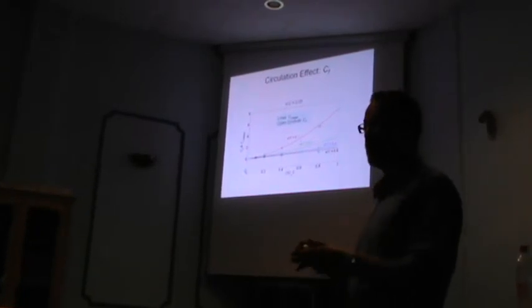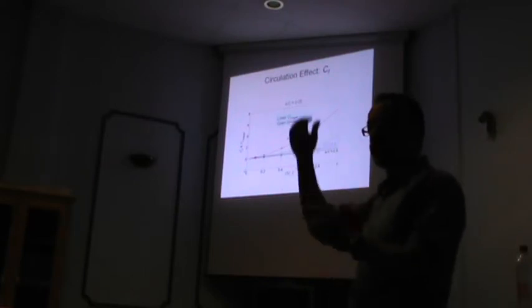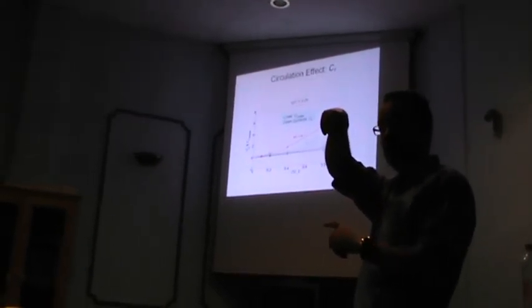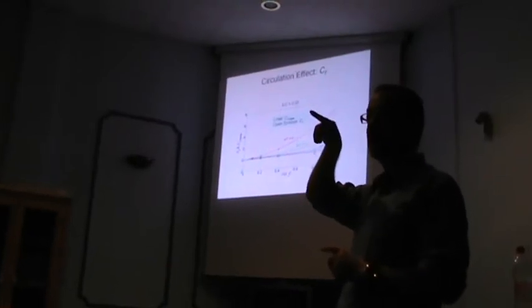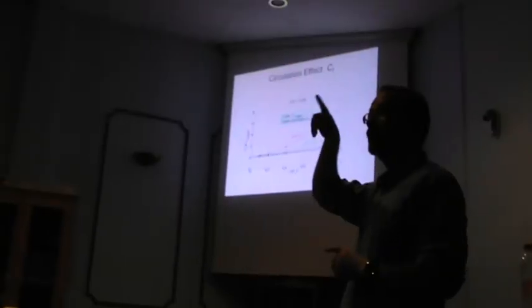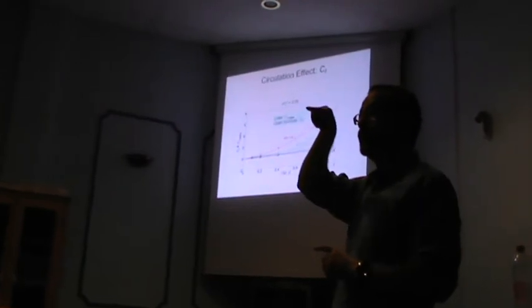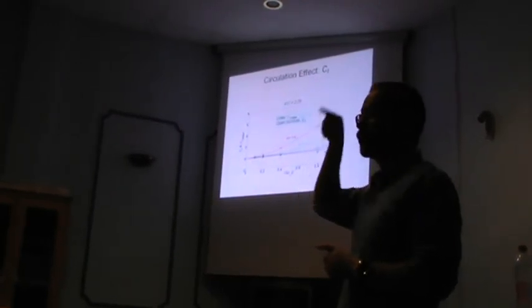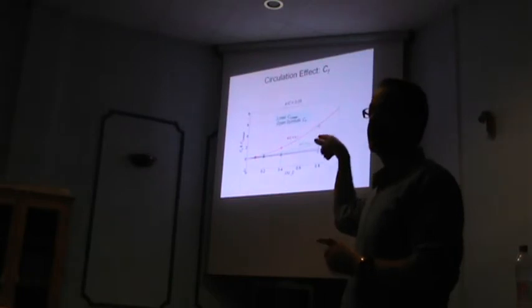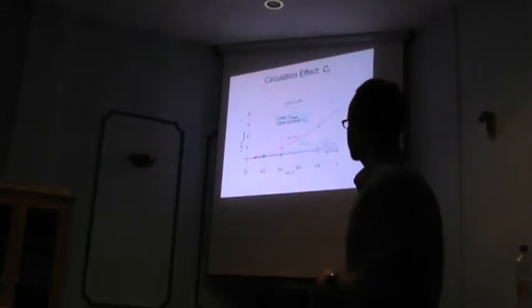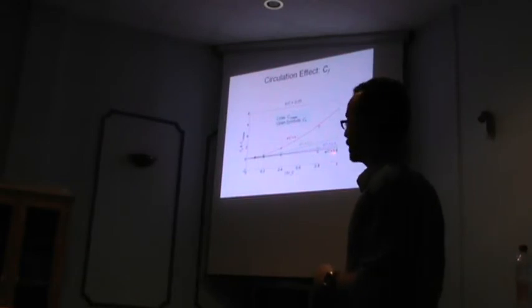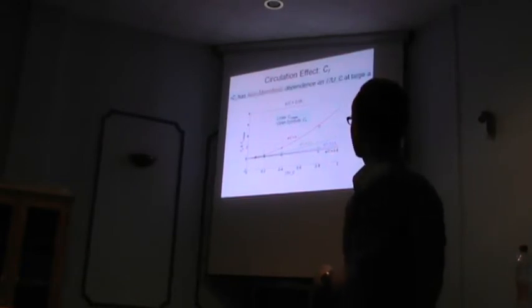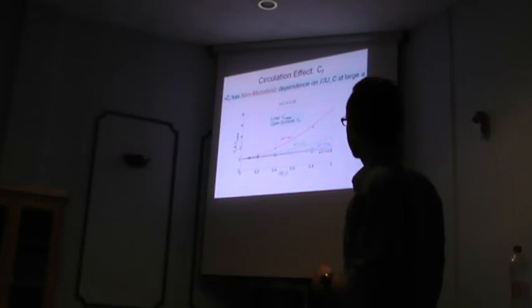The reason is, remember, as the vortex gets stronger, it's true that you get this induced flow becoming stronger, but the V component, or VRMS, of the vortex also becomes stronger. The faster the vortex spins, the lower the pressure in the core and the higher the pressure drag. And the balance between the two becomes in favor of the pressure drag at these long wavelengths. And I will show you this kind of non-monotonic dependence.